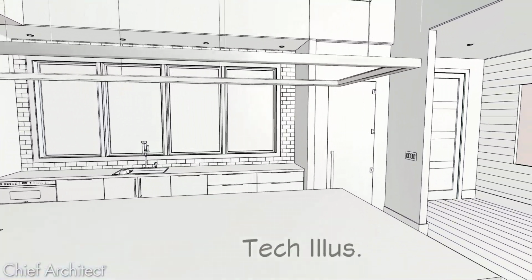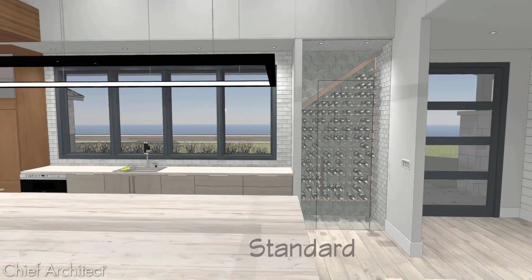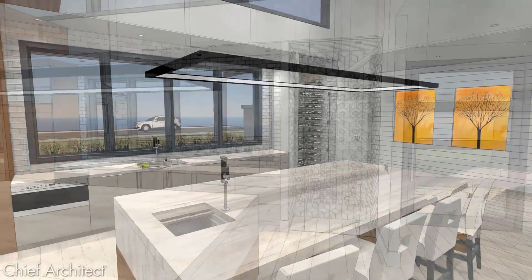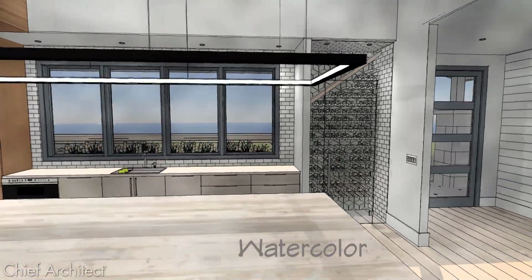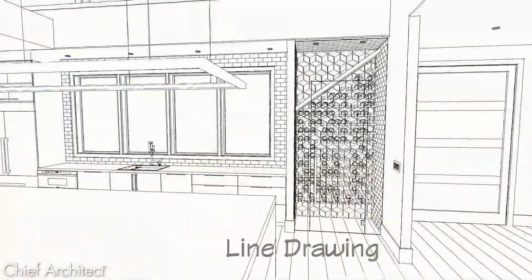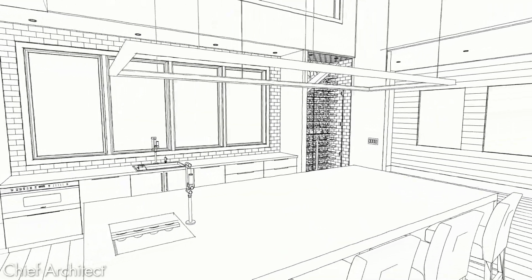I'm going to play the different recordings and we'll buzz through these a little bit, but it'll give you an idea how the different rendering techniques work. Remember, you just go into the define option, and then on the cameras, you change them to be each one of the cameras. So take a look at these and let's come back on after we've played through those.